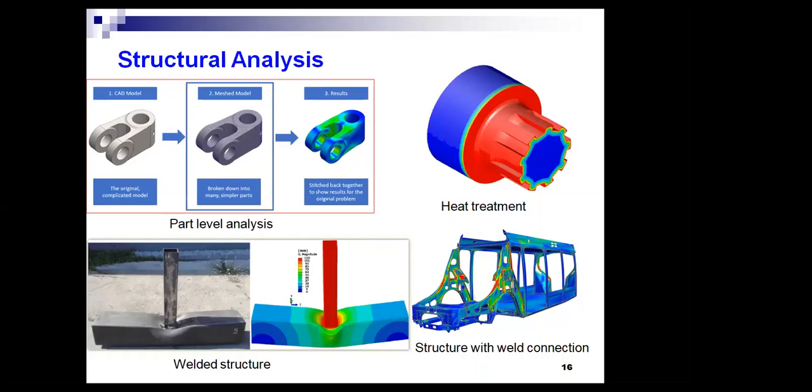And you can see the deformation after the welding process. It cannot be predicted before simulations. We cannot understand how it will deform or how much deformation will happen after the manufacturing of this product or parts through welding. So to understand the deformation behavior, a simulation will help us to implement such a manufacturing process in a virtual environment, and we can predict the system.